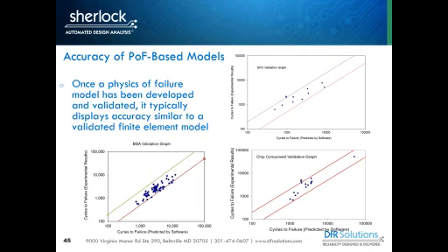We don't know exactly whether it's grain boundary sliding or void coalescence in the solder that's occurring, but do you really want to model that? Or can we say the length of the part, the thickness of the part, the materials of the part can explain my fatigue behavior. So these are just some examples of the accuracy of these types of models.